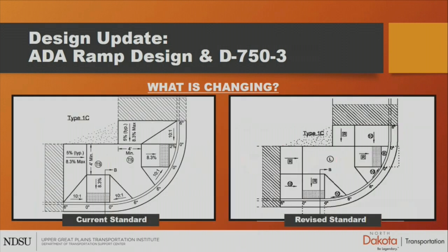With the ramp layouts, the old standard used to have a right-of-way designation on it from more or less right-of-way at the top. That's been removed on the new standard since there's other contexts that we obviously have to be considering to determine the layout of our ramps and configurations, not just the amount of right-of-way we have, which in an urban situation gets pretty limited anyways.